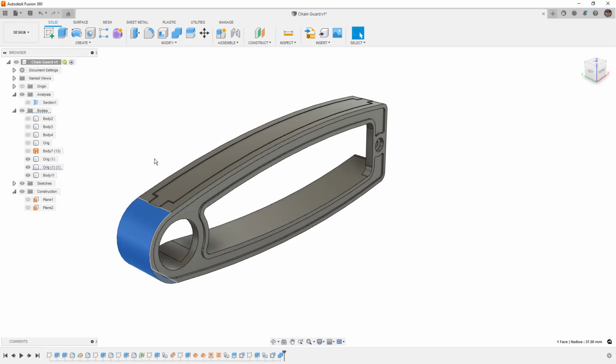Now, again, the couple of rules that I would follow: if you are shrinking or extending pieces, I would always go toward making your tools bigger and then shrinking them down. As you're removing geometry away, you know that the fit is going to be good. When you start extending stuff out, oftentimes you'll find that the extension pieces might not fit exactly how you plan.